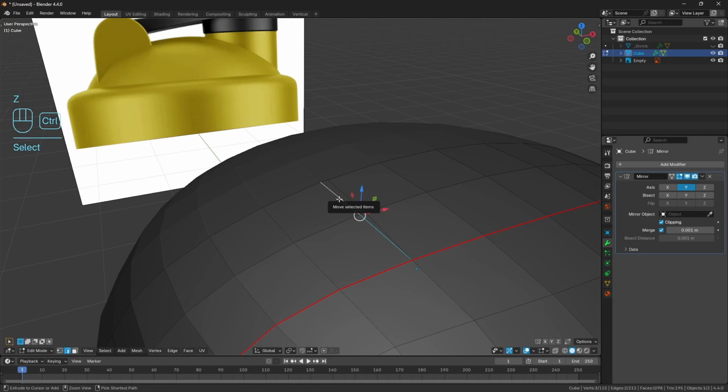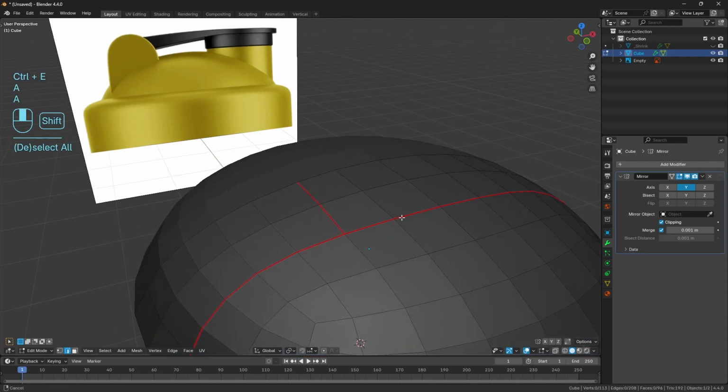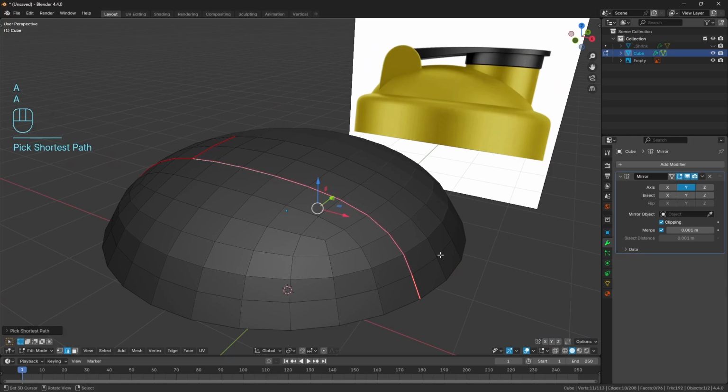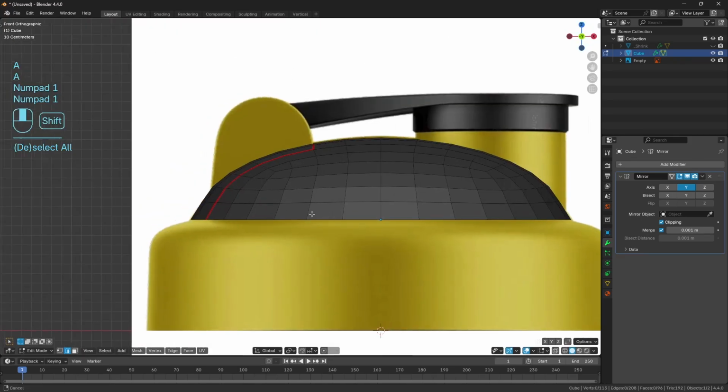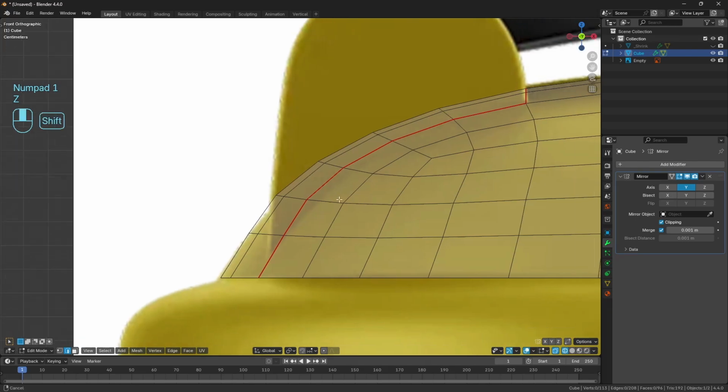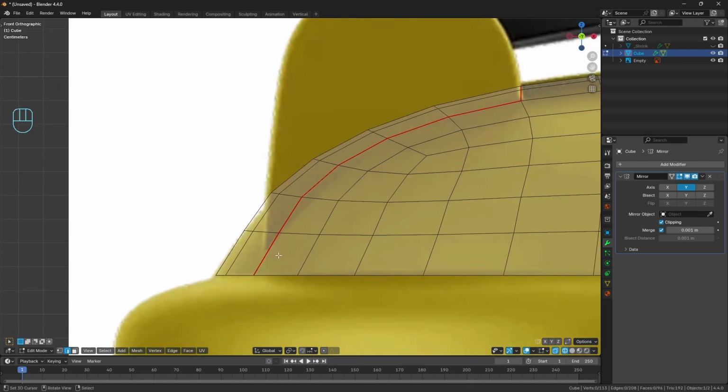And then I'm just going to dissolve the original edges there. And I'm going to mark these as sharp, once again, just to keep track of everything. And I'm going to remove these as being sharps, because that's not helping me anymore. Cool, and then at the back here, so technically we could go ahead, do Control R, cut in a loop here. I don't really think it's worth it for what we're doing.